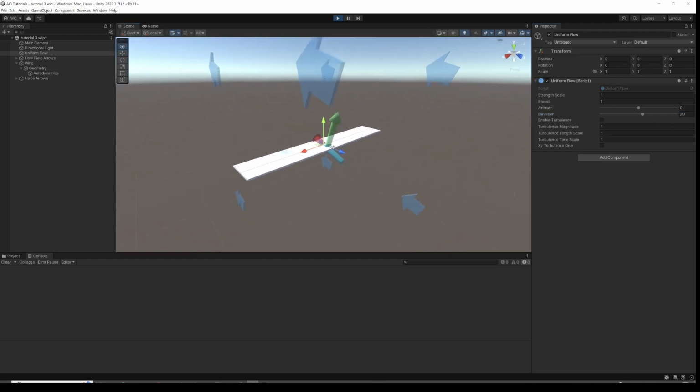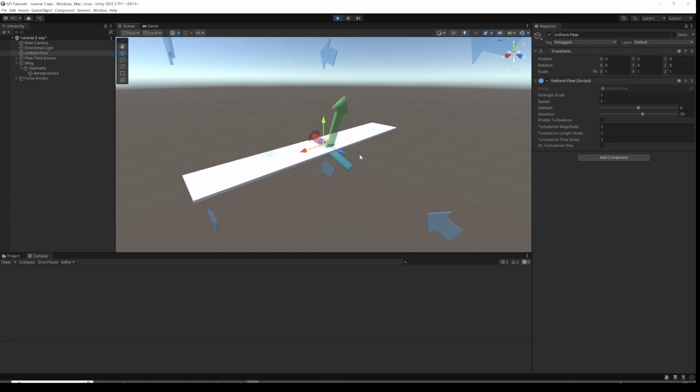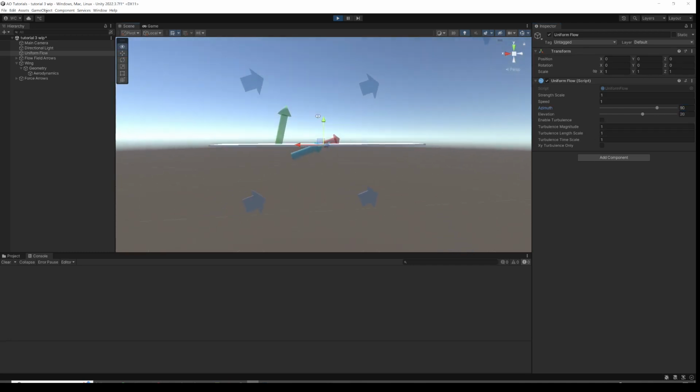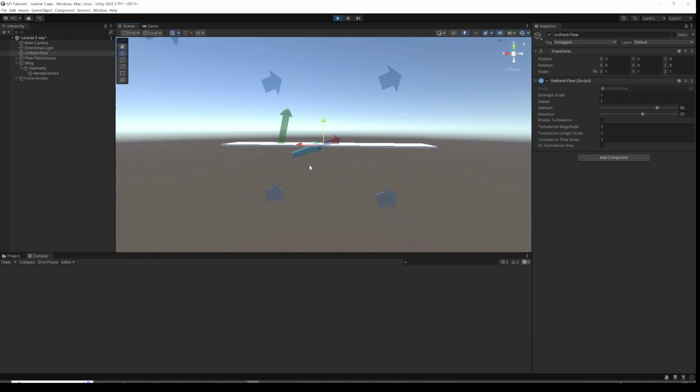The other thing we're interested in, in terms of modelling things that fly, is that if this is a wing, it won't always fly that way. It may start flying with the wind from the side. If you're a plane, you're flying in sideslip. So how does the lift vary when you change the azimuth of the wind, or the sideslip of the wing? We can do this by varying the azimuth. The wind is coming from in the plane, and as we swing it round, if we get to 90 degrees, the wind is now coming straight up the side of the wing like that.